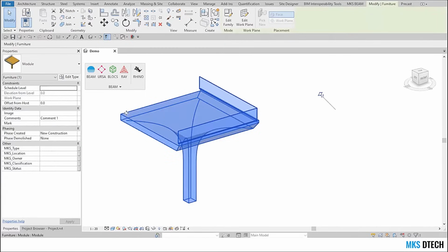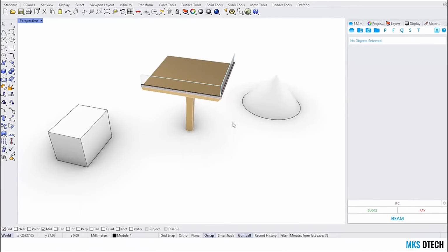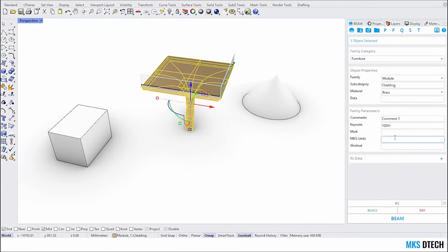When I'm assigning parameters, it's important to keep in mind the type of parameters. So if I have a numeric parameter in Rhino, I can only type numbers. Okay, so if I type some text, it will not work. Also, I have to be cautious of the units. So this file is in millimeters. So any number I type in any numeric parameter, I need to put the right value. So if it's 100 millimeters, I have to type 100.